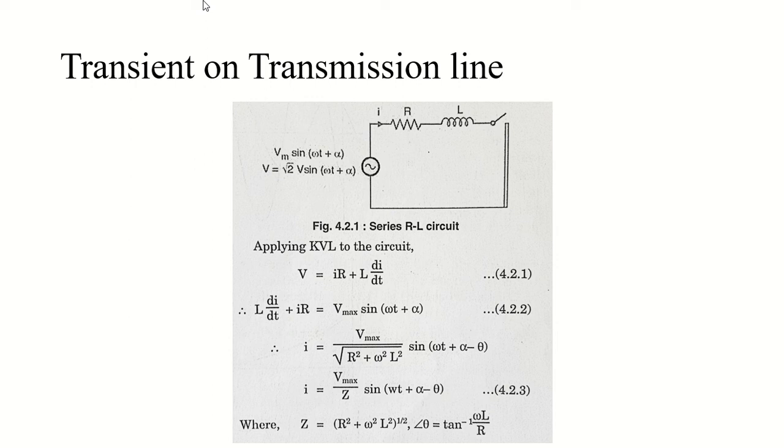But it is necessary to estimate the magnitude of current flowing through your line during the short circuit condition, so you can select the accurate circuit breaker and protective relays, because if your protective relay and circuit breaker are not accurate, then they will not be able to protect your transmission line or your substation or any equipment.